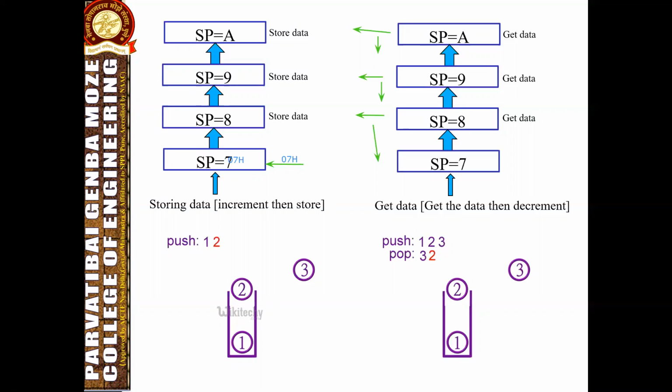That is, register bank 1 and the stack are using the same memory space. This is the information about the stack. Always the stack uses register bank 1, starting from R0 of bank 1, at address 08H.